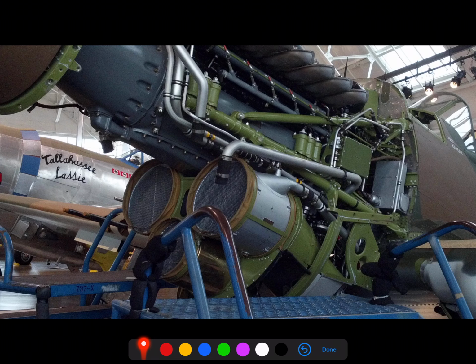Anyway, moving on. What I want to show you here is something that's very similar, or at least more similar to the type of remote oil cooler that you see depicted in the 8083 textbook. So what we have is a Curtiss P-40, and up here we have two radiators, and we have our oil cooler, which are allowing airflow to come through and mix that in with the oil that is flowing through very small passages transversely through the cooler. And then at the back, what you can see just to the back here is the tip of the flaps, which are regulating the amount of air that is flowing through these portions of the radiators.